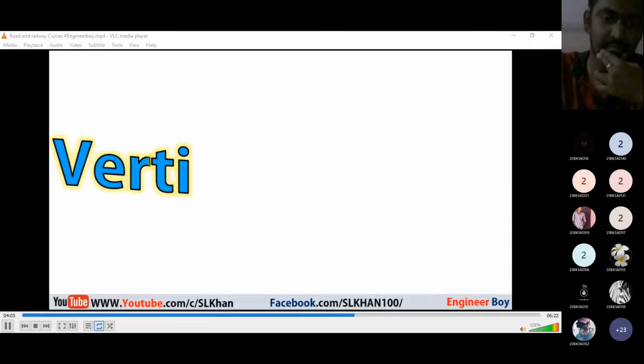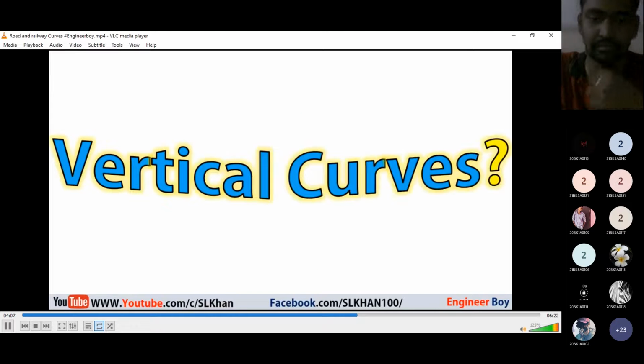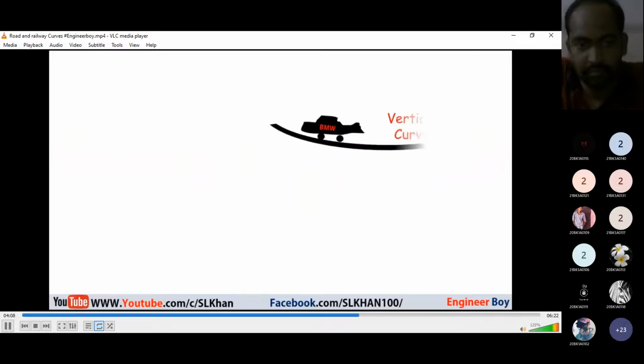And now let's talk about the vertical curves. Vertical curves are provided to change the slope in the road, which can and cannot be symmetrical. Vertical curves are parabolic, not circular like horizontal curves. Vertical curves can be in sag as well as in crest form, which depends upon the position and direction of the road alignment.